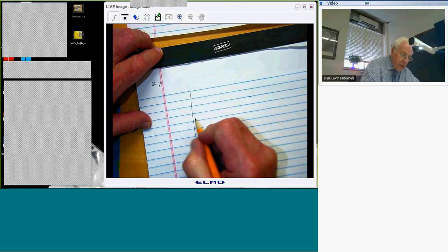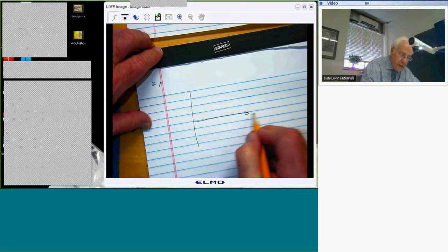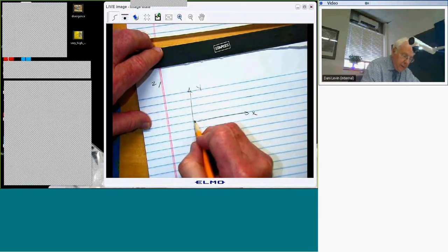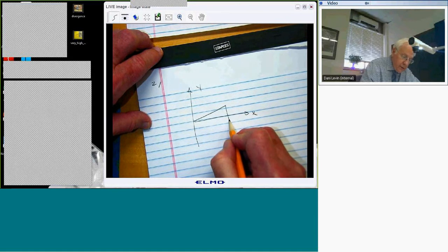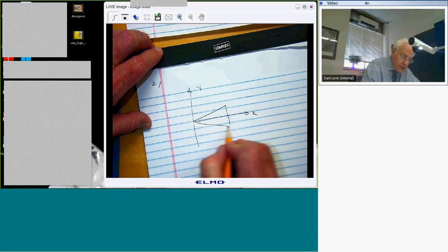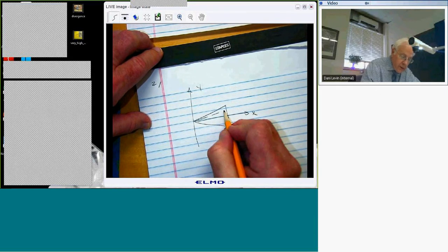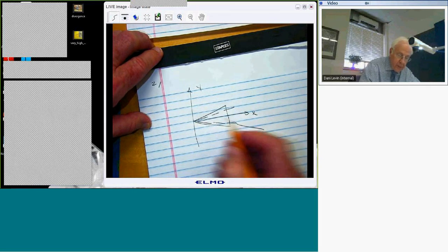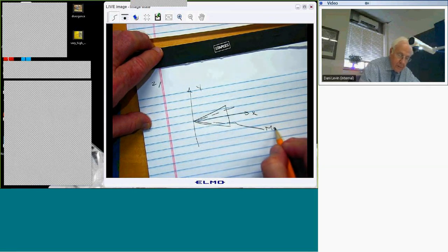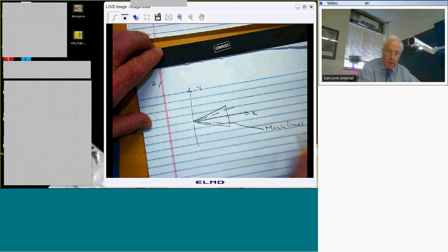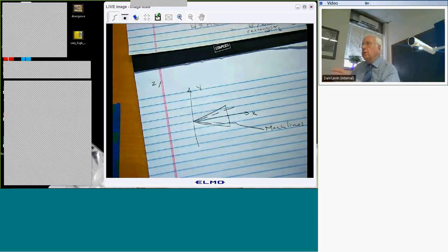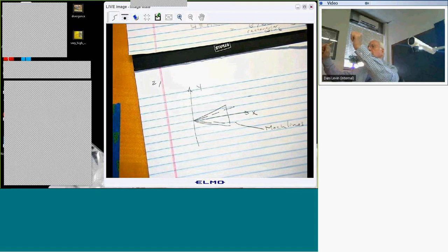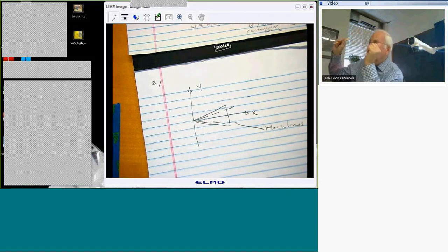We'll do it for a delta wing. So here's X, here's Y, here's a delta wing. So I'm at a Mach number so that these Mach lines coming from the tip all stay within the wing. That means the edges are supersonic. That means no flow ahead of the leading edge is disturbed. There's no disturbance in the flow ahead of the leading edge, right?